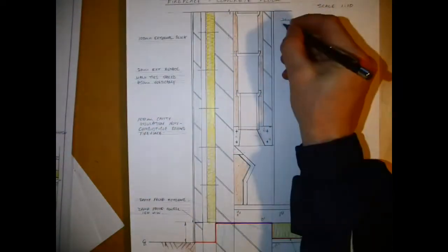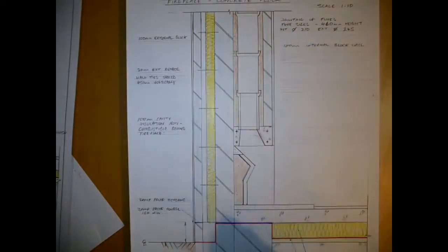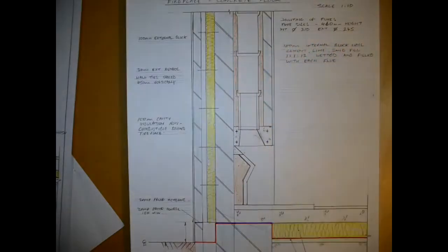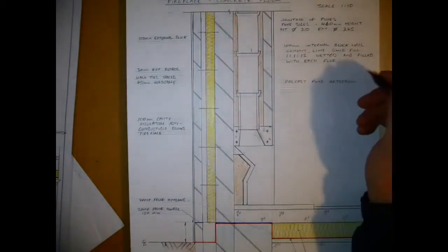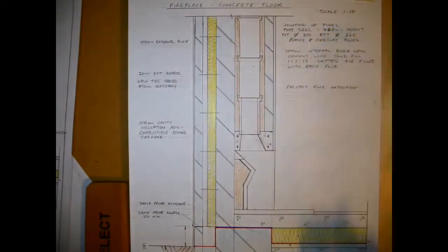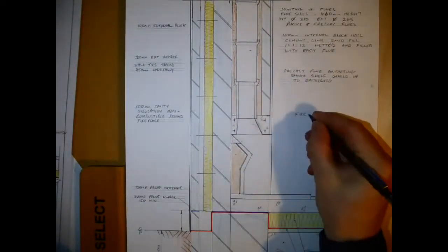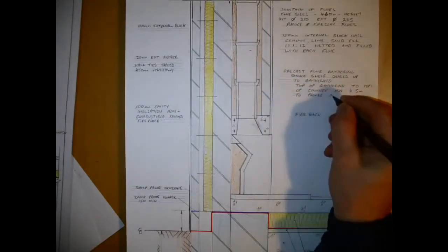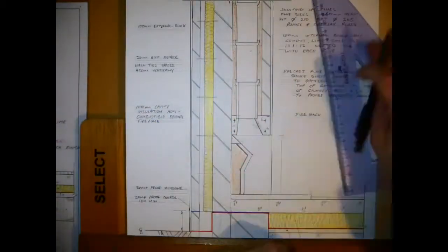When you're reading a question that's to do with fireplaces and you have to put in the detail, pick from the question the details that you must make sure that you put in. I've shown the wall ties in here as well. Simple details will get you marks that are common to every drawing, like the block wall, the foundation, your wall ties spaced at 450 centres, and the very first piece, and the common mistake as well with insulation. The insulation cannot start to be built in, or the fill insulation can't start to be filled in until the DPC and thereafter. So that's a detail often incorrectly done.